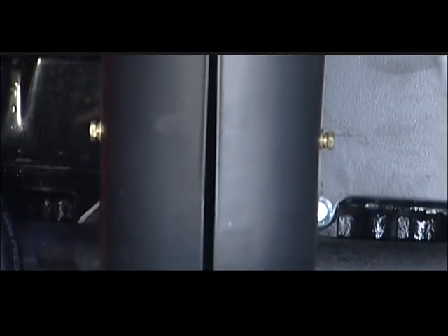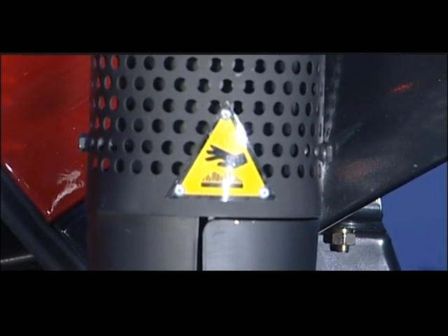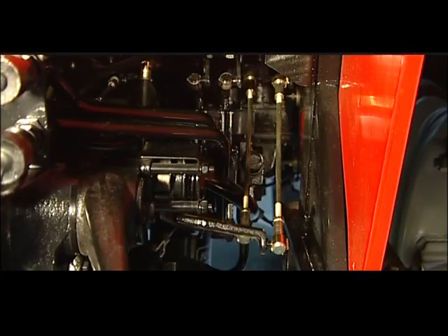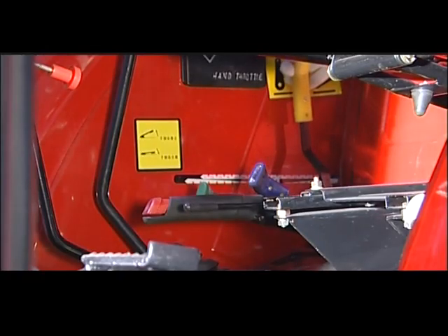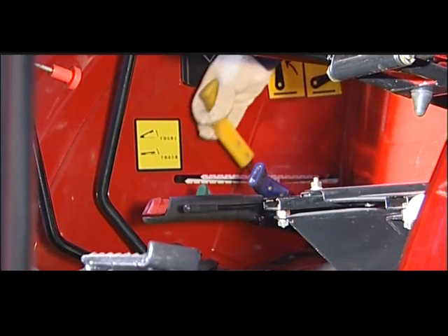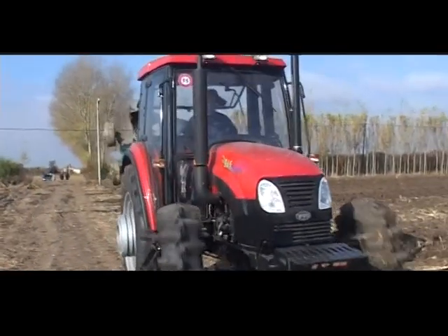Prevent being scalded while draining oil or approaching the high temperature sections of diesel engine. Forbid to remove the pipes when there is still pressure in the hydraulic system. Stop the machine, move the hydraulic operation lever to and from for several times. Release the pressure in the pipes.